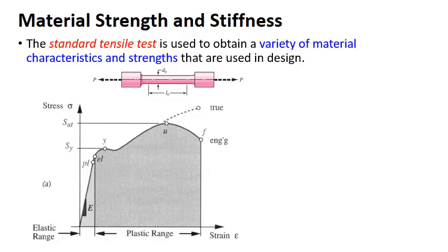In fact, no one can determine it exactly, because measuring elastic deformation involves very small strains. Elastic strains are very small. To measure that, you need a highly precise extensometer, which is very difficult to manufacture. But here, for the purpose of understanding, it is kind of exaggerated, and it is mentioned here. EL is the elastic limit, and Y is the yield point, corresponding to SY, the yield strength. We use SY. Please look into the notations. And U is the ultimate tensile strength, or just tensile strength,